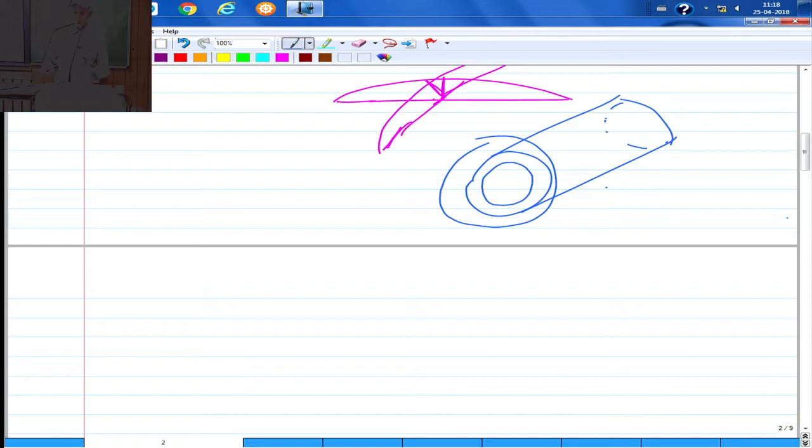So if you have this as a cell structure, along the whole circumference, of course the displacement can vary along length, but at a particular axial location, the whole cross section is either expanding or contracting. So this is known as the axisymmetric mode of vibration. Depending on the length direction, if the boundary condition along this edge and along this edge are identical, their distribution along the longitudinal direction can be classified as either symmetric or antisymmetric.